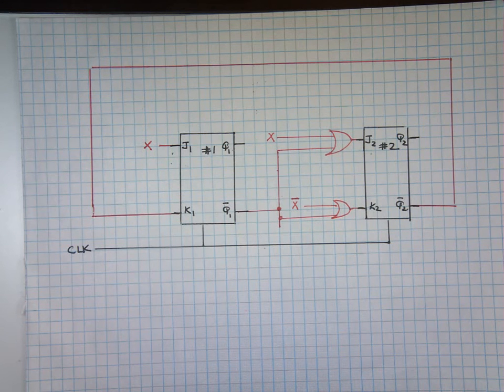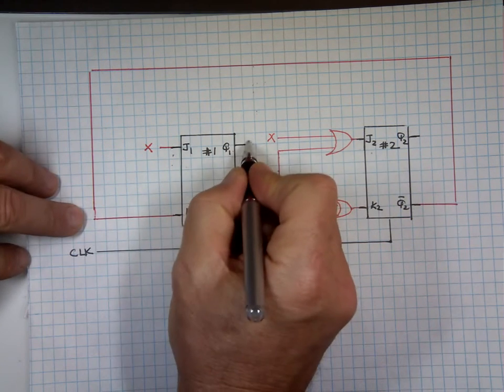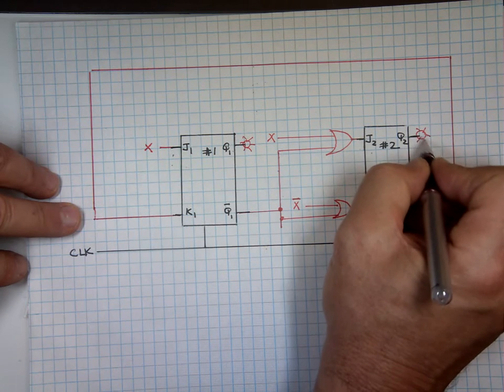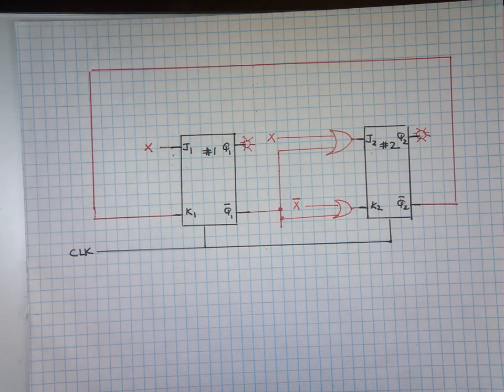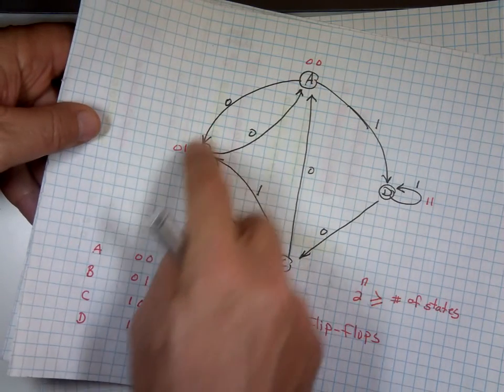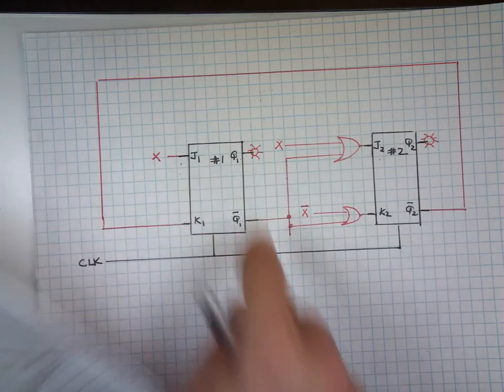There's only one input, and that's X. So notice my output, which is in this case the next state, that's what my output is. Again, if I put an LED here, light, to see if the light's going to be on and off. Initially, if I'm at 0, 0, if I preset these, make them go to 0, the lights are off. And I go, okay, let's make X be 0. Well, if I'm at 0 and I make X 0, what should happen here? Based on this one, it should go 0, 1, right? So the light should stay off, but this will go to 1.